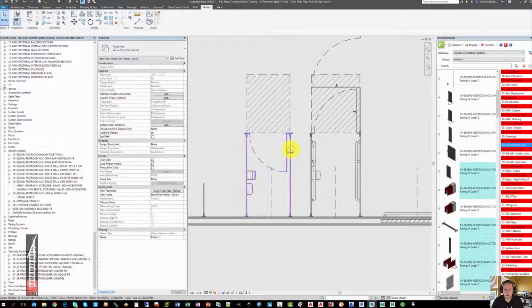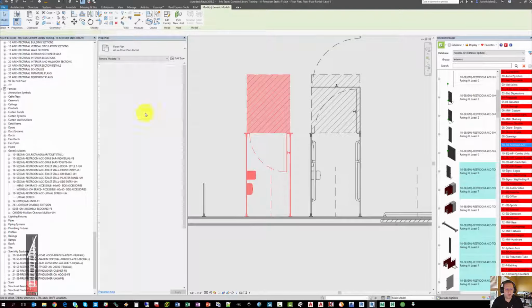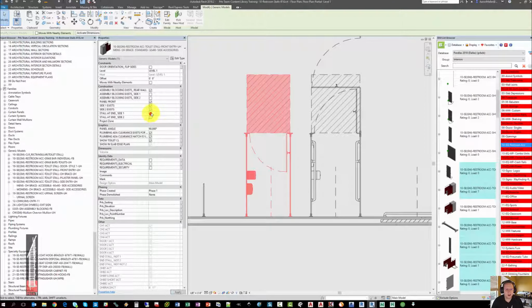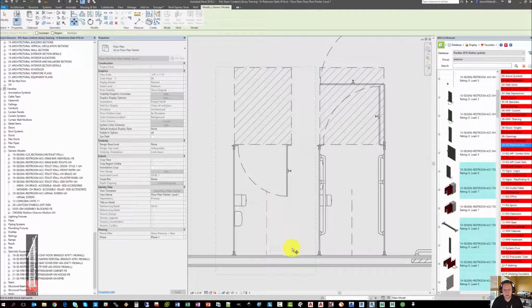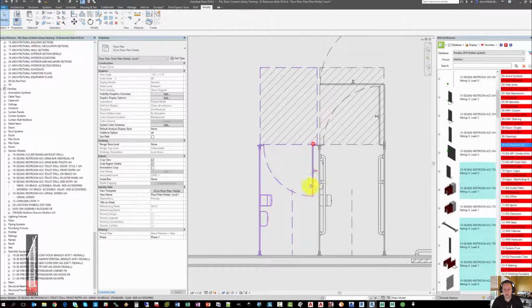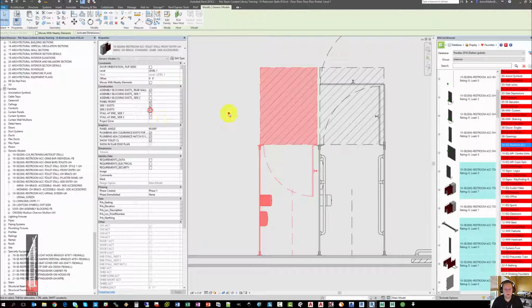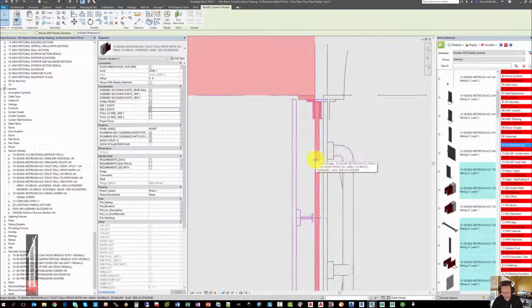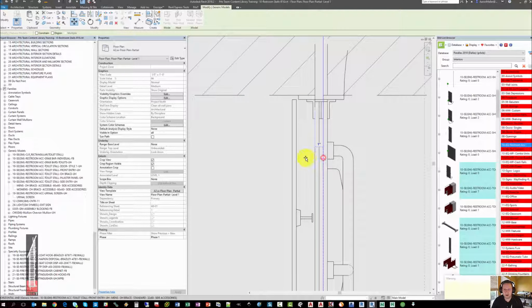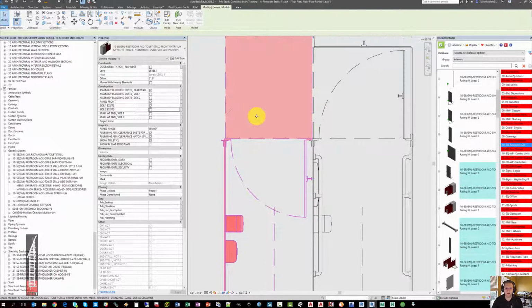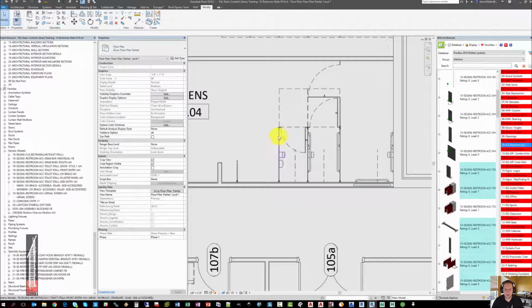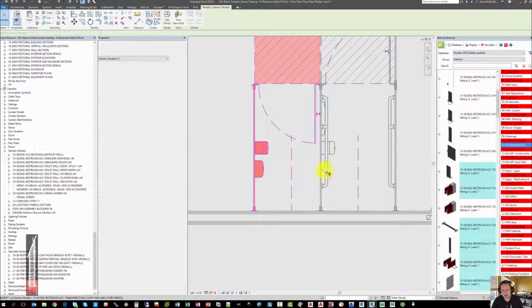And now we can take our typical stall, and we can do the same thing. Say side 2 does not exist, and move the stall into position. Not in the correct spot, of course. We'll move that into the correct spot, and then turn off side 2 exists. There we go. Now, if you wanted another one of these stalls, you could simply copy it as you did before.